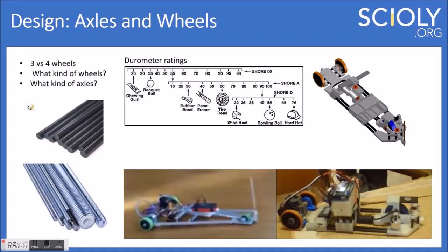If you can use electronics, it doesn't really matter so much because the threaded rods were really just used for wing nut systems, and that is their primary use. But if you don't need a wing nut system like we didn't, the carbon fiber rods are actually quite good. They have a very low rotational inertia. They're very light, very strong, very malleable. So you can use them for other things if you need to modify them for whatever reason. And they do fit the ball bearings, I think they're like 22 millimeter diameter ball bearings. They fit them perfectly, like the standard bearings, which makes it very easy when you're trying to figure out how to construct everything.